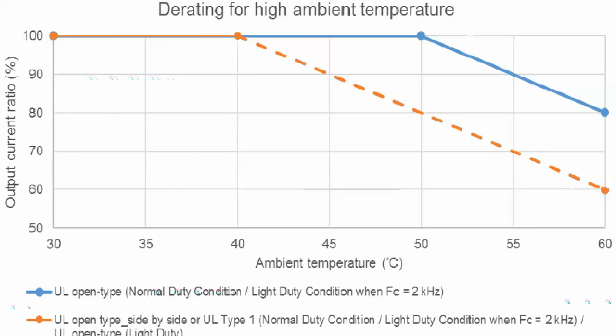So you will have, again, to take the rated current of the drive and multiply it by the derating factor for 8 kilohertz. Depending on the model, we'll have to derate by either 87% or 84%.